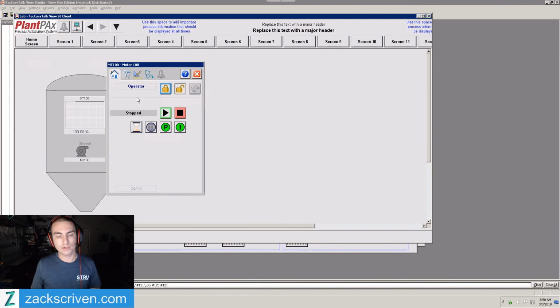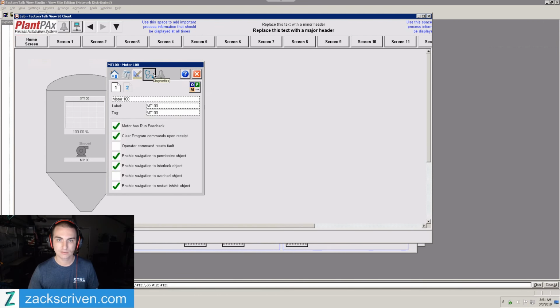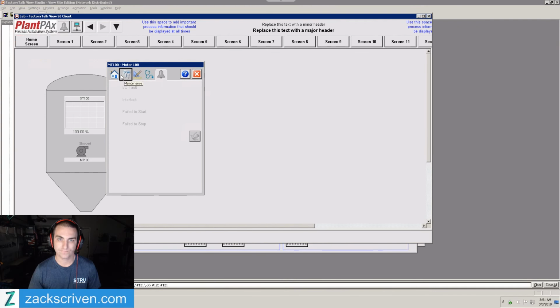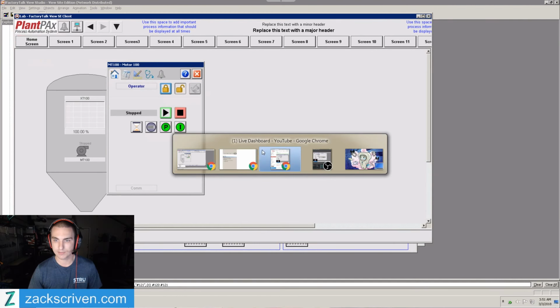Now I think it's important to know how to do a pump AOI. I think that's an important process to go through, but after you've learned it for the sake of learning it, there's no reason to go through each project that you do and create your own add-on instruction. I know probably everyone has their own libraries that they use or copy and paste from previous projects, but why not use a library that's standardized for Allen Bradley, has a ton of features built in, has nice faceplates. So, I think it's pretty awesome. So let's get back to the lab here.